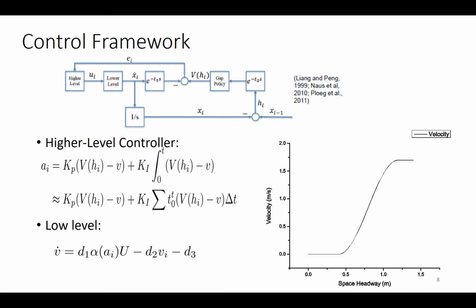The framework for velocity control is the same for both kinds of cars. For the control system of the car, there are 2 levels. The high level is to calculate the next acceleration based on difference between the current velocity and the expected velocity. Then, the lower level control could use these parameters to calculate the next PWM.